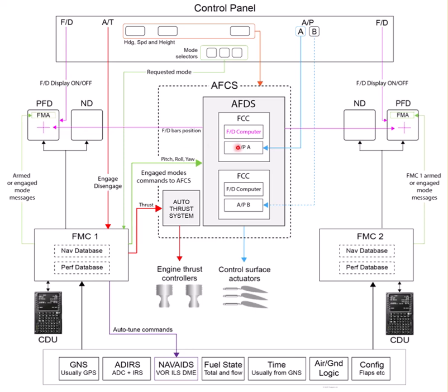Okay, so we've now got the flight director, which shows me everything's going fine, assuming the autopilot's okay. I've got the autopilot, which is flying the aircraft on the flying control surfaces. I've got the auto throttle now doing the engine thrust, so it's looking to see what I've pressed up here, and if it's relevant to the auto throttle, then it will do something. If it's relevant to the autopilot, which of course it usually is, it will do something. So let's introduce the LNAV and VNAV buttons now, because we've got everything we need.